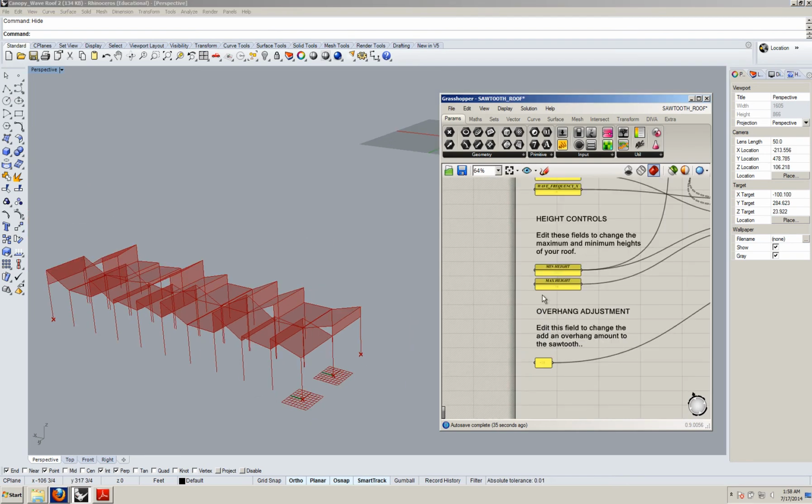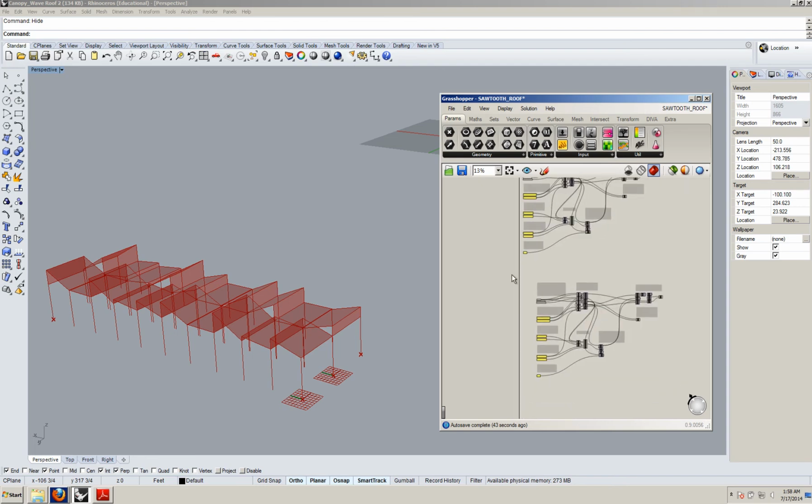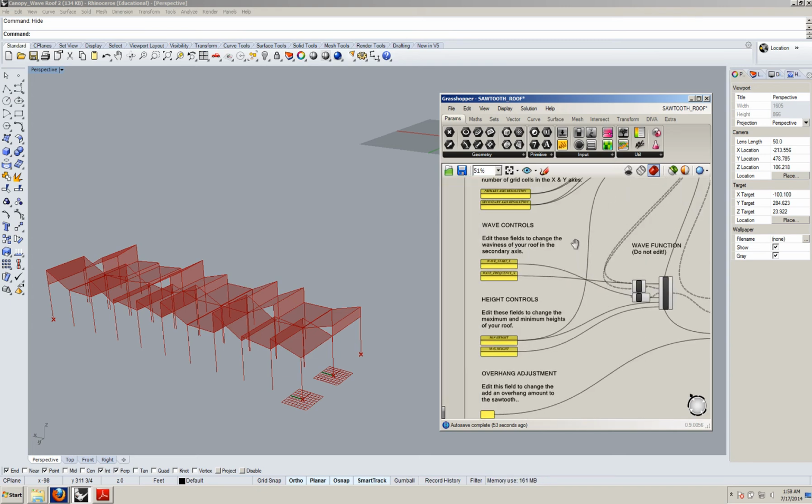Again, at the end of the day, you would need to bake the lines and the planes, in this case now in both sets of parameters. And you would bake those into Rhino, again remembering that you would want them to be organized by layer. So that's more or less how the given Grasshopper definition works.